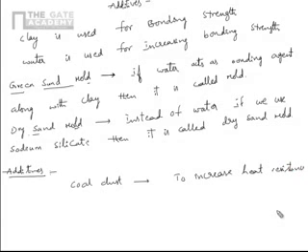The mold has to withstand the higher temperatures of the molten metal, so for that, by adding coal dust, it increases the heat resistance of the mold to withstand the higher temperatures.